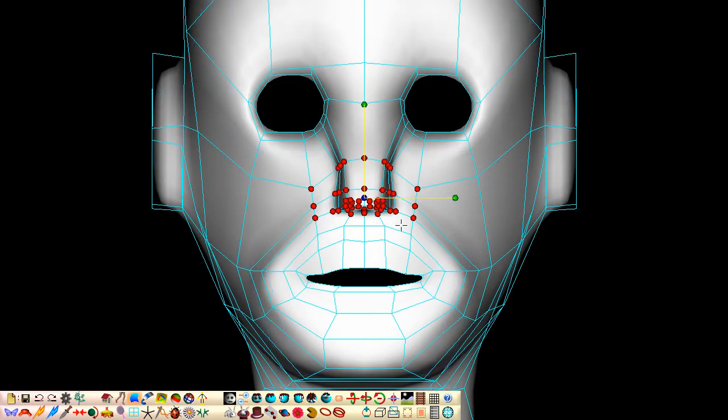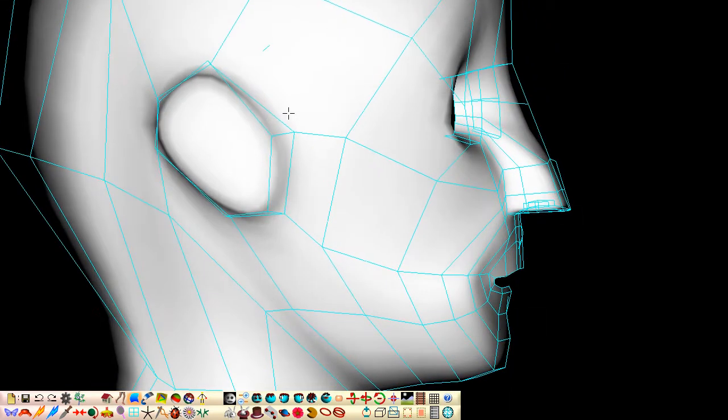To unselect points, hold down both the left Control and left Shift keys while dragging out the rectangle. You can unselect all of the control points by clicking on empty space while holding down the left Shift key.